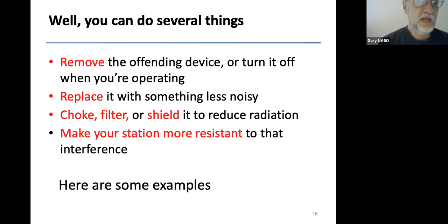First thing you want to do, if you can, is just simply remove the device or turn it off. For instance, I have some noisy fluorescent light ballasts in my shop, so I just don't turn those on when I'm operating. So if it's my equipment, I can just turn it off. Or maybe you have those new LED lights in the counter in the kitchen, and maybe again they're noisy, but you can just turn them off. Maybe you can